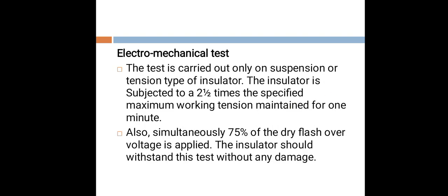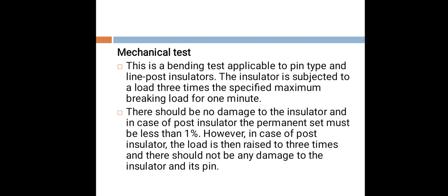Electromechanical test. The test is carried out only on suspension or tension type insulators. The insulator is subjected to 2.5 times the specified maximum working tension, maintained for 1 minute. Also, simultaneously, 75% of the dry flashover voltage is applied. The insulator should withstand this test without any damage.